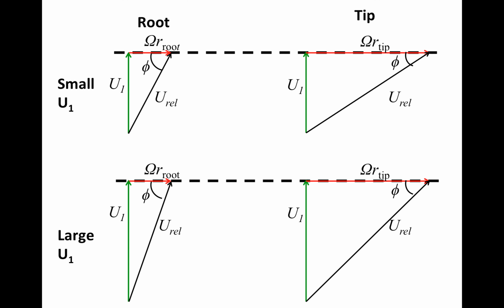So even without an active pitch control system, the fixed pitch wind turbine can be designed in a way such that when the wind speed exceeds the rated speed, larger and larger portions of the blades will automatically enter the stall regime. And this is called passive stall.